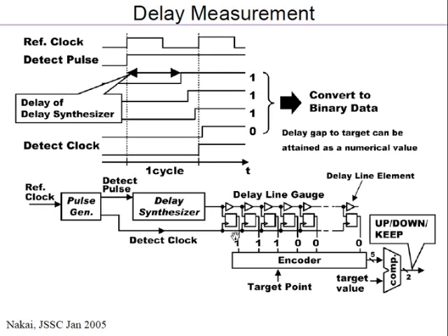So when you capture it, you will get, say, 1, 1, 1, 0, 0, 0. Let us say you had a signal here which was going from 0 to 1. What that means is that at the next edge, when you get this 1, 1, 1, 0, what you can infer is that this edge is somewhere here.